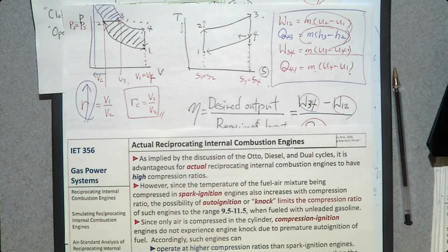On the other hand, when you have a diesel engine, we only have air in the engine. So we compress as much as we can. Then we inject fuel, so it self-ignites, and we can achieve a higher compression ratio. So higher MPG can be achieved when you have a diesel engine.